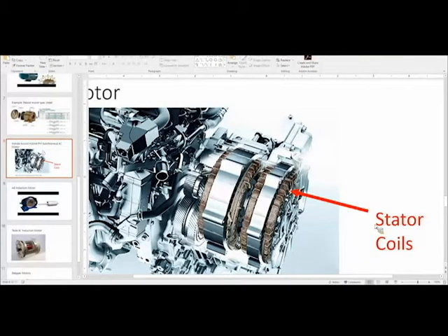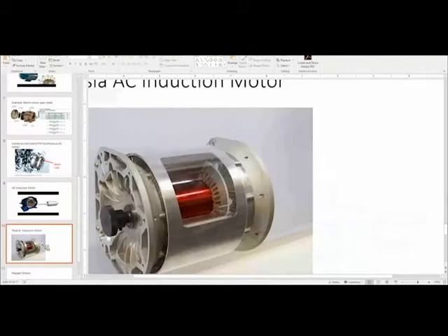And so in terms of having a supply chain that's stable and that you can always rely on, they went with this induction type motor. If you look at the components of this, it's basically coiled wire, copper, not an issue there, other types of ferrous materials, and that's about it. In terms of sourcing, that's something that we do with hundreds of industries in the United States all the time. So they went with the AC induction motor with this one. But the Model 3 is back to using permanent magnets. I'm not sure what the rationale was for that, why they have different ones, but they have different motors for different product lines.